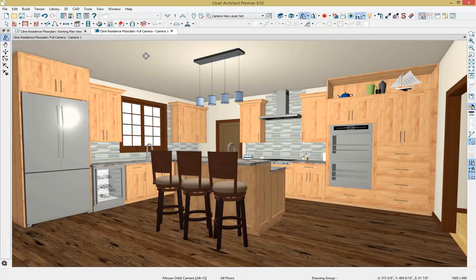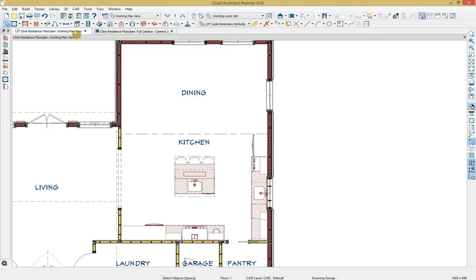Going back to our floor plan view, let's go ahead and add some can lights to our ceiling. To add lights to these two rooms, I'm going to go up to our electrical tools right here in our toolbar, and from the drop down we select a light, and then I'm just going to come into our plan and just click once where I want a light to be.